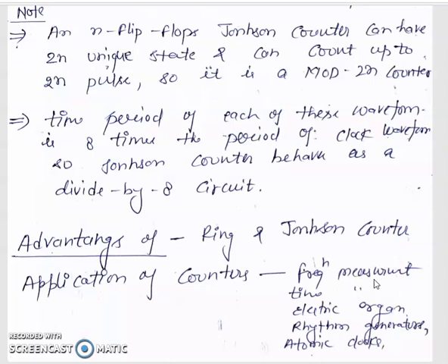videos for the counter. The basic start is the asynchronous counter. There is the 2-bit asynchronous counter, 4-bit up and down, 4-bit asynchronous counter, for the up counter as well as the down counter. After that we are familiar with the synchronous counter, which is also an up counter as well as a down counter, and we selected the mode for up and down in a common circuit.